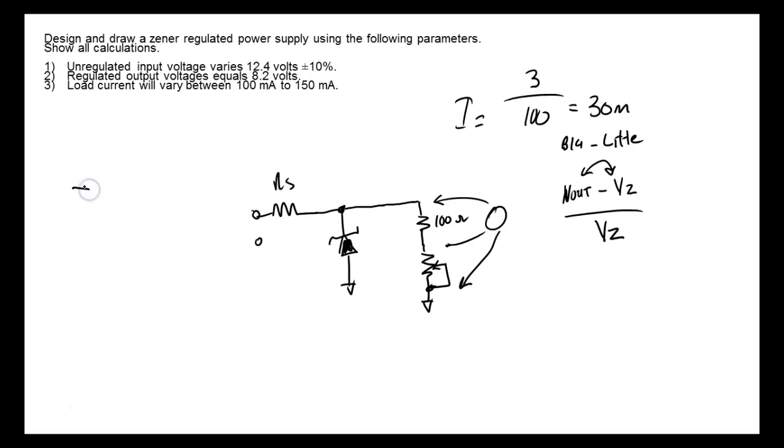So they'll come over here and they'll have a DC power supply, and then we have one resistor. What they'll do is put their meter on volts and measure volts. Then they'll come over here and break the circuit and measure amps. Then they hook up another circuit and their meter's still on what? Amps. And they put it across that resistor, and what does it do? Blows the fuse.